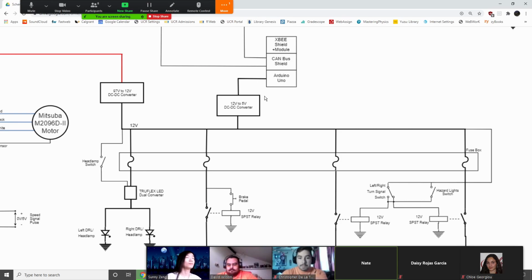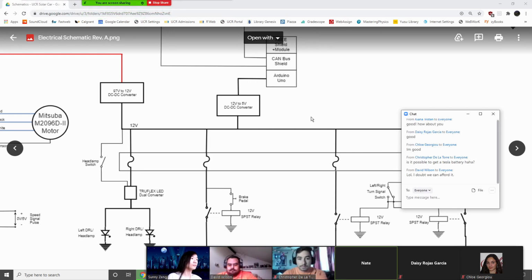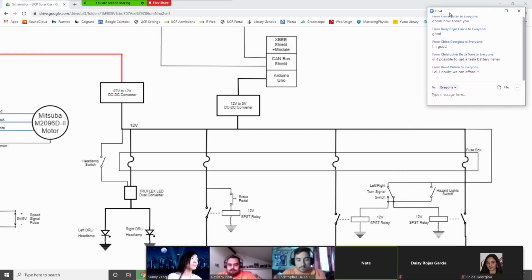Serial communication is basically the opposite of parallel communication, where you have many nodes branching off of a single microcontroller. I'm assuming most of you have at least seen a microcontroller, a little black rectangular box that you would put on a breadboard, and it's got a bunch of nodes on it. You can have 8 of those nodes represent an 8-bit binary string, and you can connect that to another system. Depending on which of those wires are high and low, you'll have a different message being sent out. With serial communication, it's that, but under a single wire. So essentially, one wire will be communicating between 2 microcontrollers in this example.